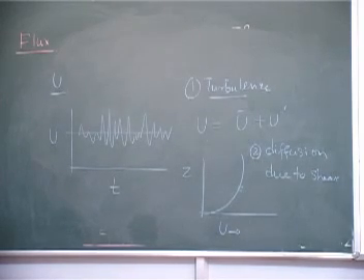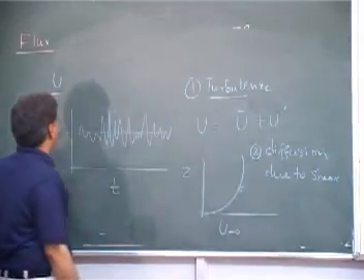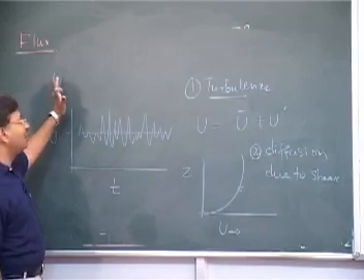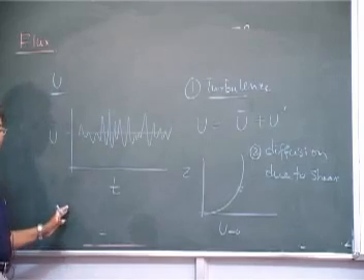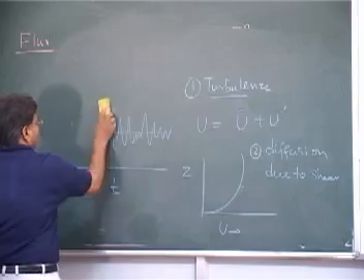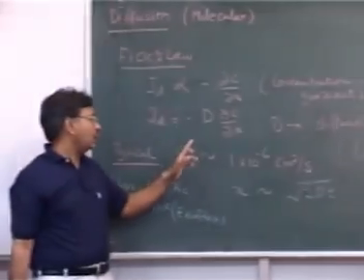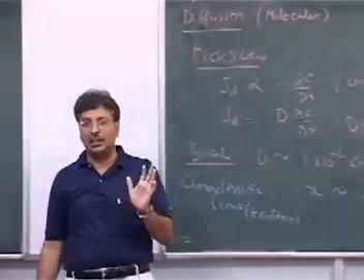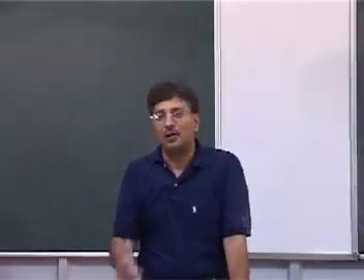So that's what we have to consider in our next calculation, that if we really want to find out what will happen to the pollutants when they travel from Delhi to Kanpur, they are not going to disperse just by 4 mm or whatever number we got, but much more. So let's say we utilize this knowledge. If you say this D will vary, then with your knowledge of the last two classes, D will depend on what?